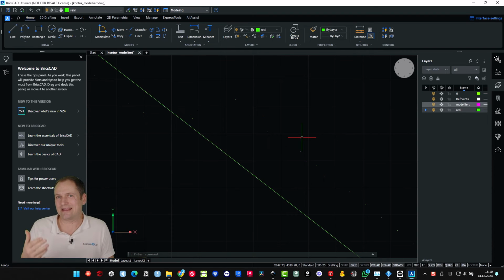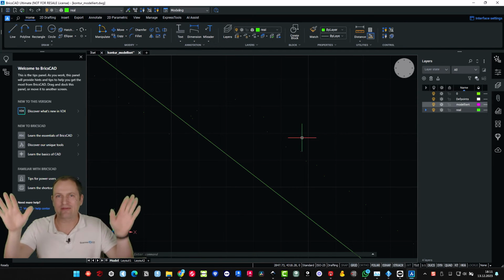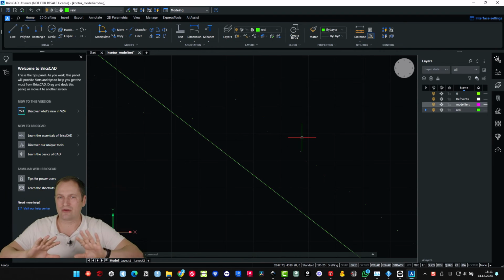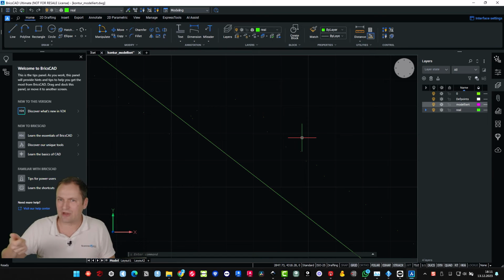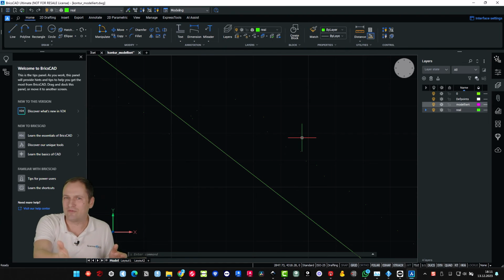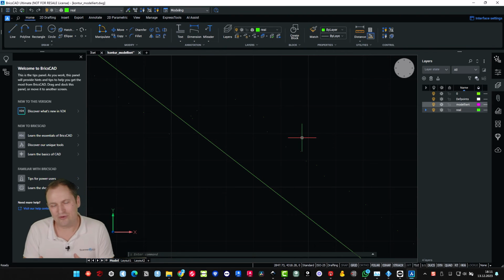And then think about your walls. You can measure the noise if the walls are totally flat. In many cases, you have some structure on the wall, and then of course you will see the structure with the scanner. But people coming from tape measure or from disto laser measurement never thought about the fact that the deviation on the wall is now visible. So don't waste too much time on it.